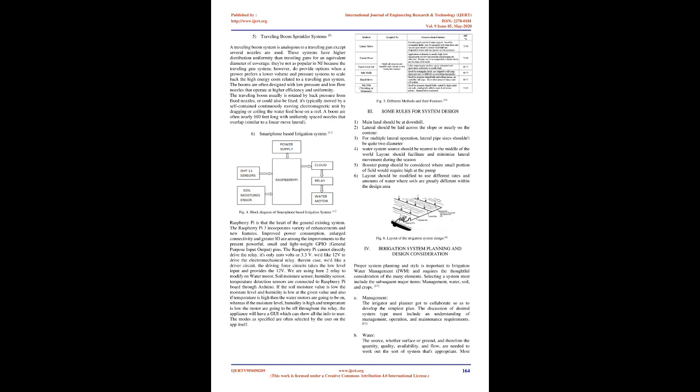These include using low-energy precision application, LEPA, and low-pressure in-canopy, LPIC, systems. LEPA systems, precision application, require adequate, implemented soil, water, and plant management. LPIC systems are used on lower-value crops where localized water translocation is suitable, 30 feet before or behind the lateral position.